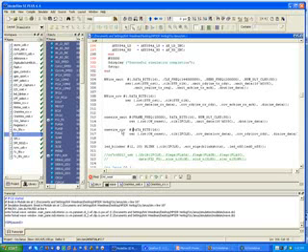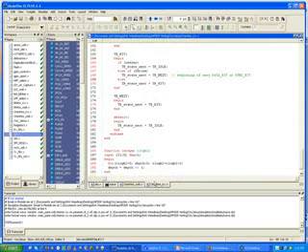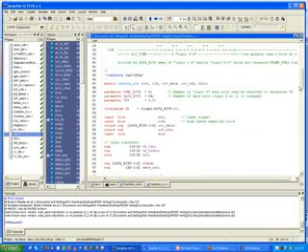No, I'm doing an instantiation here. The pound sign in this case means that I'm going to override a parameter. I'm just instantiating a module. Let's go back to our receive, and I said data bits, and I said 16. So what I'm wanting to do is override this parameter. Instead of it being a module that receives 64 bits, I want it to receive 16. So that's why I call it a parameterized module.